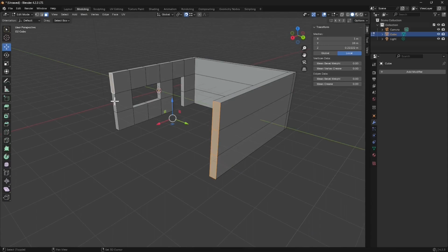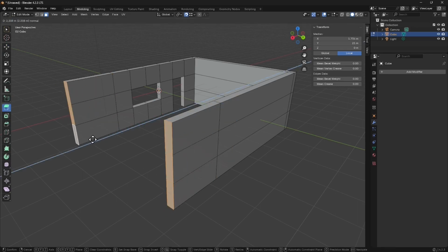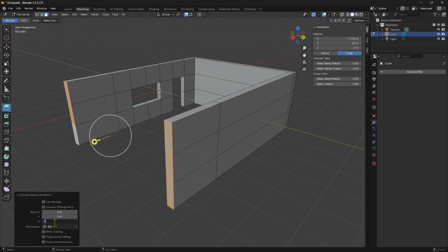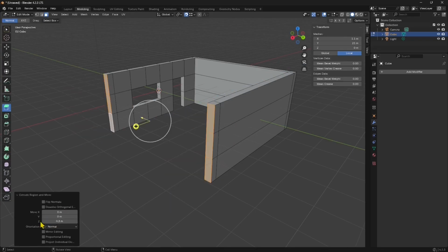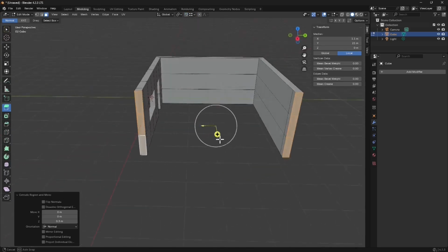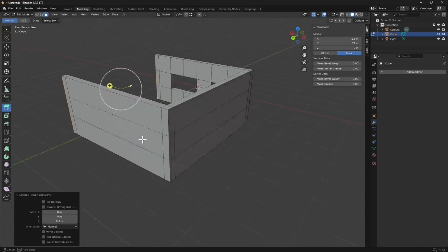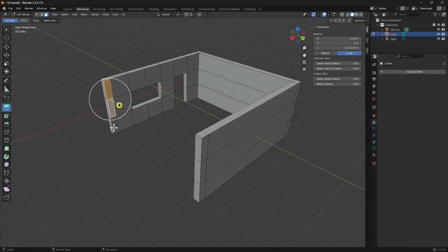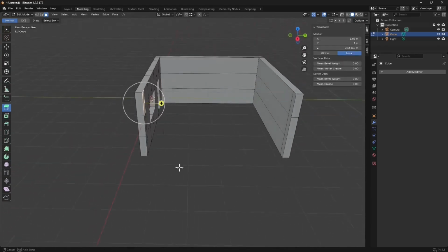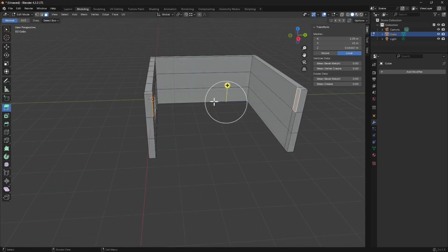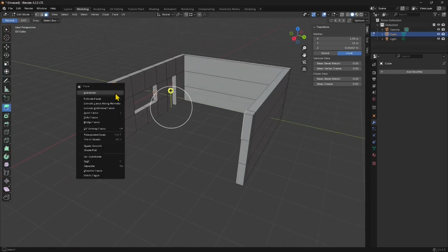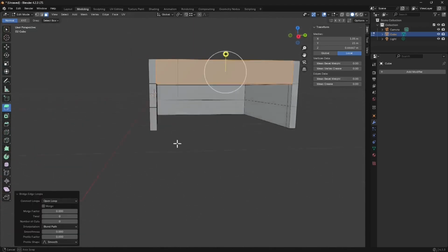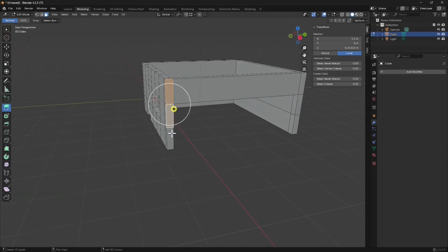Now, if I select again these three on the other side, so on both sides, I need to extrude, and now I can do a bridge. So let me just change this into 0.3 so I can create an internal wall or an internal opening. So deactivate the snap because they're going to get in the way, certainly. So just turn it on when they are needed. If I select just one of these faces and I do bridge, I can create a beam passing through the house. So this is a beam, and then those two are the pillars or structural wall.